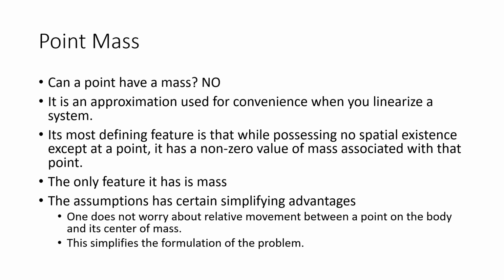And take, for instance, a shaft in a mechanical system. This shaft may have possibly a 10 kilogram load acting at one end. Now, if I were to look at this as a physical object, I'll have to draw the shaft and apply the 10 kilogram load at one end. But if, on the other hand, I look at it as a point mass, I need to find the center of mass of this shaft and just apply the 10 kilogram load there. The fact that it is at one end is no longer significant once I have made the point mass assumption.